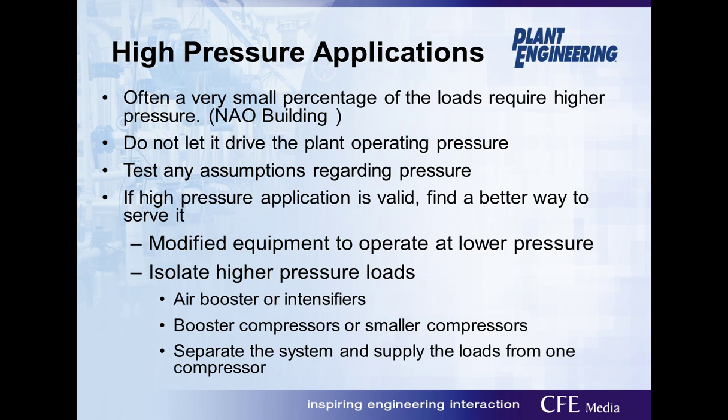I was going around expecting to find the normal stuff you find in office buildings. And then I went downstairs into the executive garage and found that they had an air compressor running at anywhere between 95 to 110 psi, driving the entire system, which for things like controls, you need maybe 30 at max, even with that big of a building.